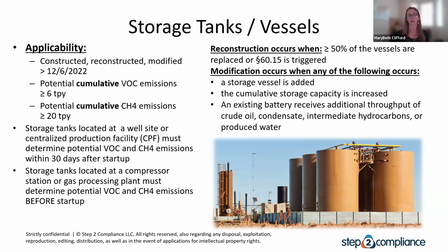So your applicability is based on your potential cumulative VOC emissions and your potential cumulative methane emissions. And whereas in Quad OA you only did your potential to emit on VOCs, in Quad OB you're going to calculate your potential to emit for both VOC and methane emissions.